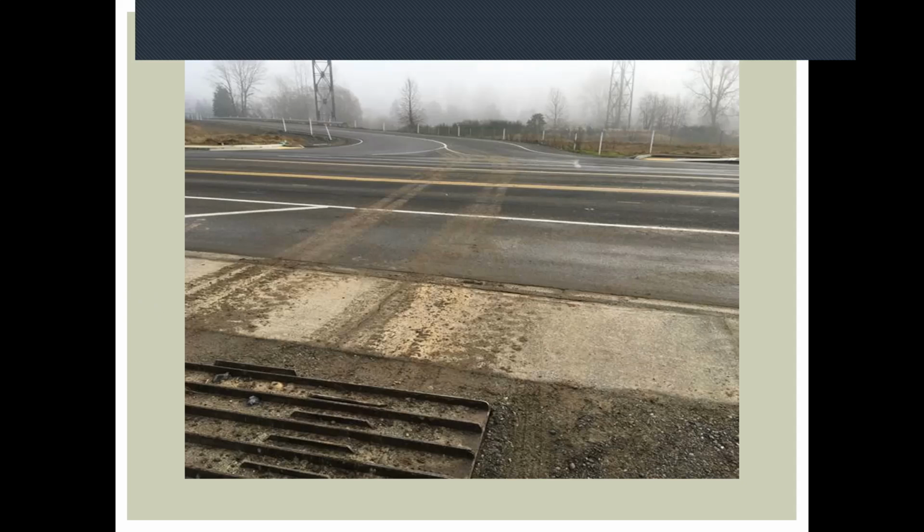Where I worked at the Port of Seattle, no visible track-out was allowed. So this is a violation of the contract. Fortunately, not a port project, but be aware that once tires are dirty on a project, there's no sediment control that's going to take care of it before the trucks leave. So it doesn't matter if you use grizzlies, you use rock. If the tires go on it dirty, they're going to go out dirty. So it's either site management, watch where people go, or have haul roads and trucks stay on haul roads, or have a tire wash, things like that.